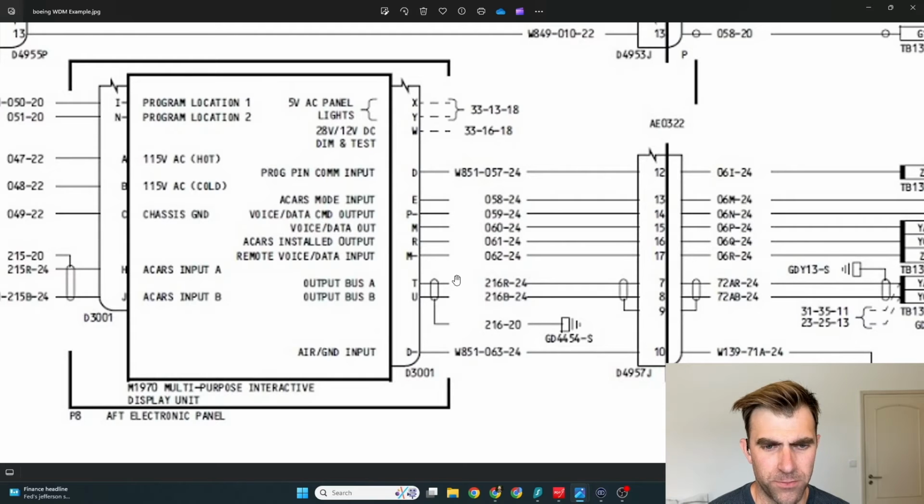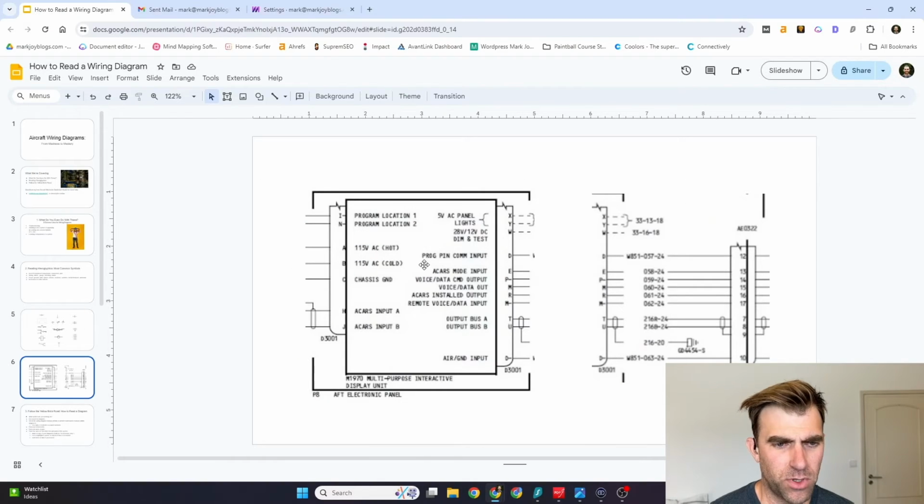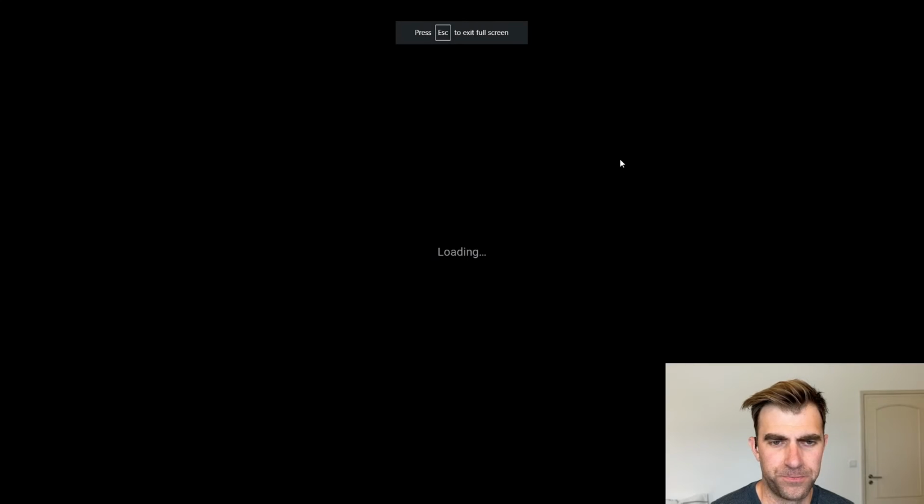And then you've got a twisted pair here, like I mentioned before. You can see the two conductors with the shielding going around, and then the shield is drained here. So this is a 20 gauge wire that's taken to ground. Here's your ground symbol. So that's what the wire labels look like. All right, so let me pop back over to my slides here.